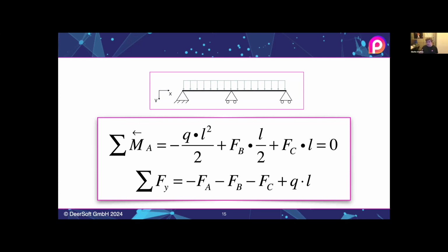So now it becomes a little bit of high school math. If you have 3 unknown values and only 2 equations, then you can't solve it. That's a limitation just by math. The normal rigging math that you have doesn't allow you to solve this. So now it becomes a little bit more challenging. In order to calculate the forces onto this thing, we need to make it more complicated.